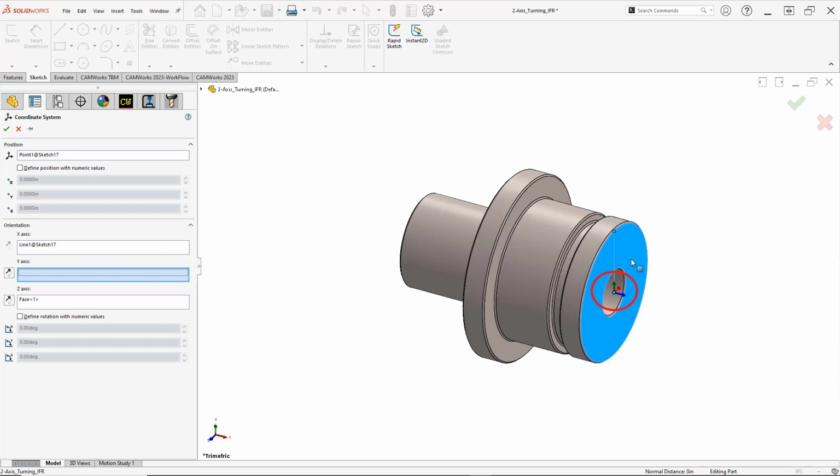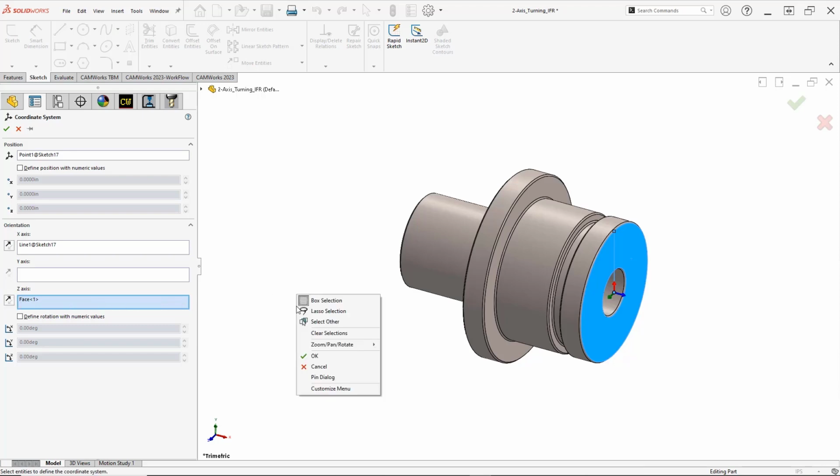red, and blue help determine proper orientation, and it is the same colors used for the SOLIDWORKS reference triad. Toggle the reverse direction icons to achieve the desired result as shown in the SOLIDWORKS display area. Once done, right-click, then select the green checkmark or OK, as this will confirm these existing settings.